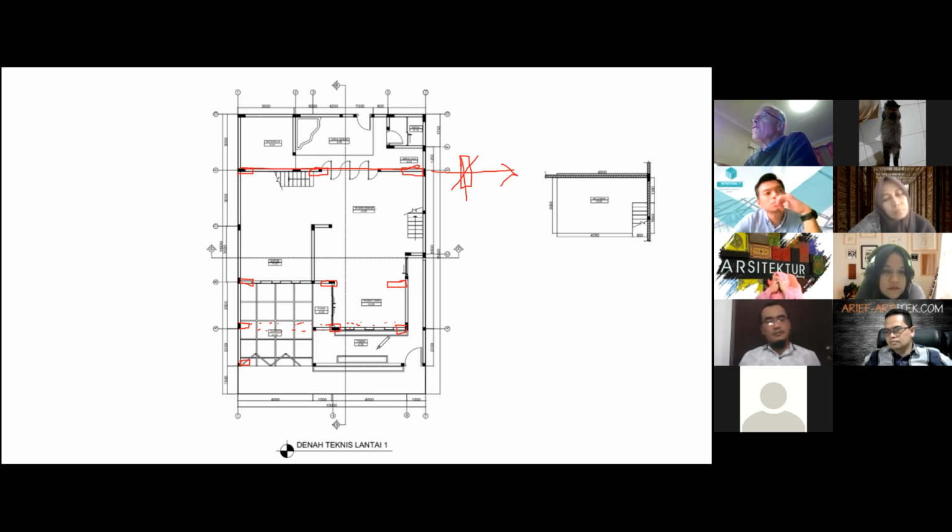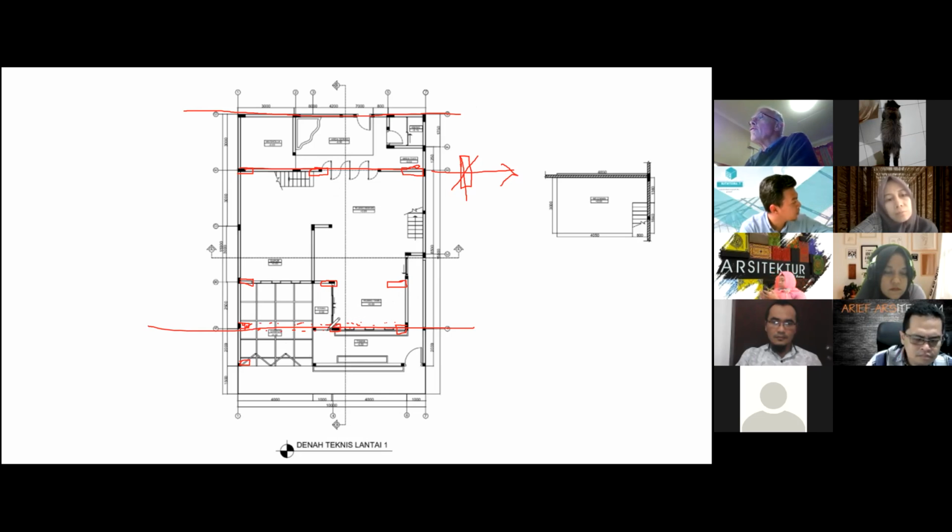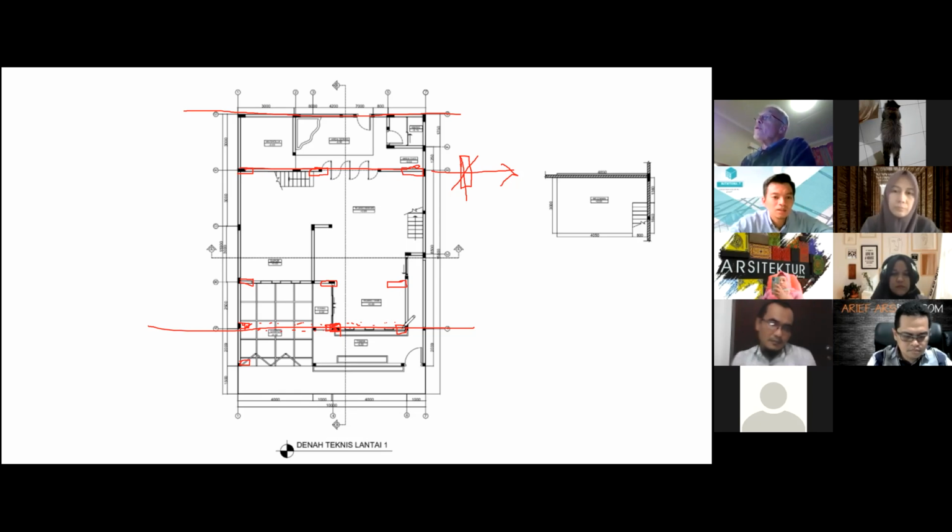But, you know, to me, it would be quite feasible. I mean, I suppose you can see that it's better just to have two frames, a moment frame here and a moment frame, say, on this grid G. And then it's reasonably easy to accommodate, you know, a total of 6 large columns. So that's my suggested solution that the student could use to bring this house up to, you know, a standard where the house would be safe in earthquakes.